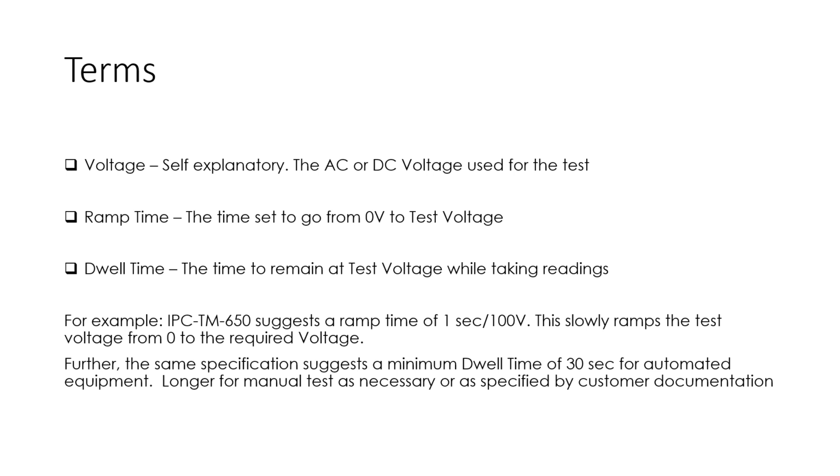The main reason is that if we do have a problem in the dielectrics, as we start to ramp up, the system is watching that, and if we see any leakage detected or a short, immediately the system will fault at that point, and we won't even get up to test voltage, so that there won't be any significant damage to the PCB or an arcing that could be hard on the equipment, or if it was a manual test, the operator, if they happen to be close by.